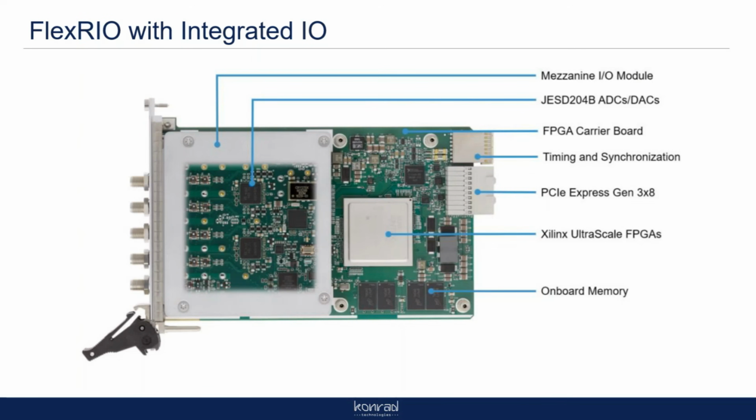All right. So for those who don't know, FlexRIO is a type of card, and it's probably 5-10 years ago now. It's been a while since they released these first ones. The idea of FlexRIO was NI wanted to have a standard backbone FPGA card that they could put these front-end cards on. They call them mezzanine IO modules, or you'll hear them called daughter cards from NI.